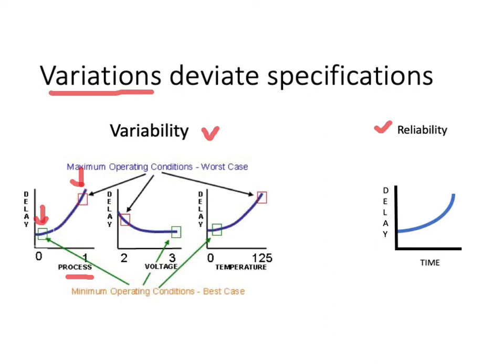Okay, and there are another class of variations that are introduced between integrated circuits, and that is due to differences in the operating condition of the circuit, the situation under which you operate the integrated circuit. So voltage may be applied differently on the circuit, but it's not really the small differences in supply voltage that really matter in this case. It's rather the dynamic changes in voltage as we actually switch from logic 1 to logic 0. So in digital circuits, they tend to be operating at least hundreds of megahertz, and nowadays in the gigahertz regime. So there are many switching operations.